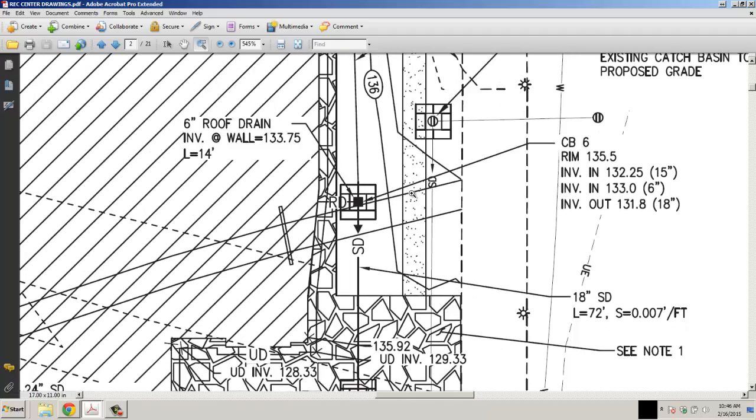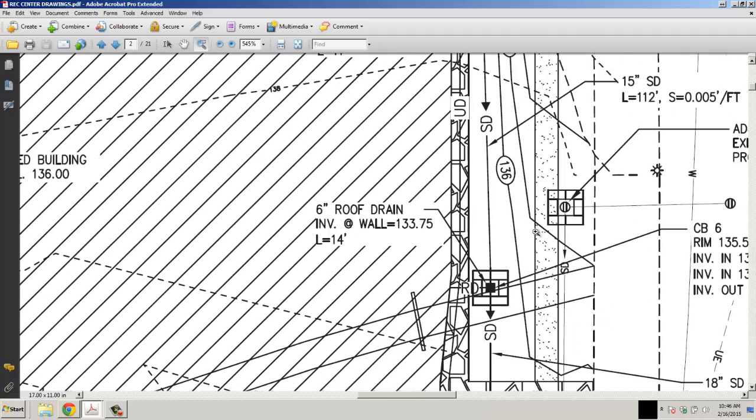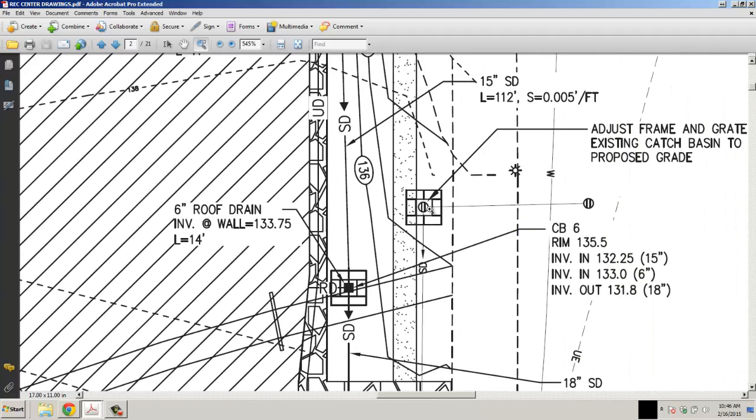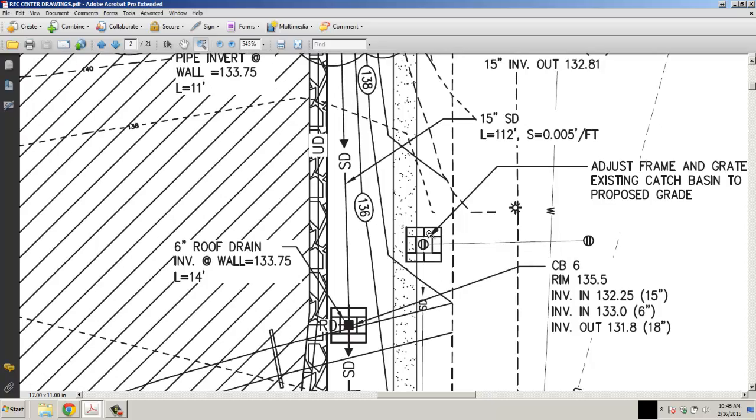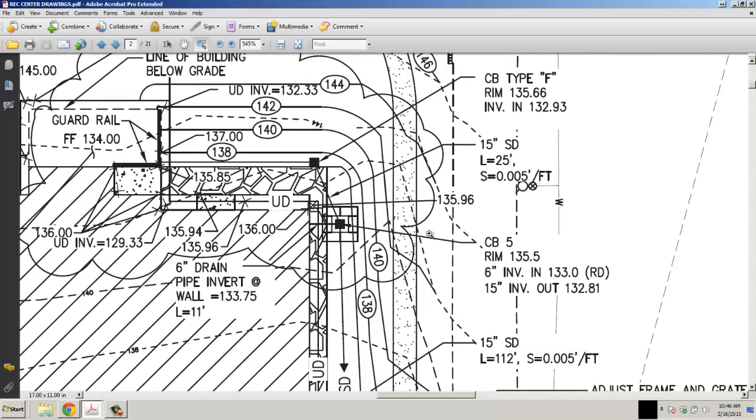SD is a storm drain, so you can see all these catch basins. There's one right up here just outside the sidewalk underneath those stones that has an outflow going down into the catch basin. If we look up here in the upper corners, we can see some more outlying materials, mostly your inverts and your outflow.